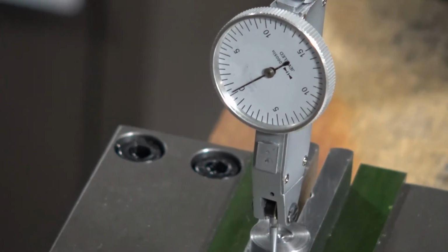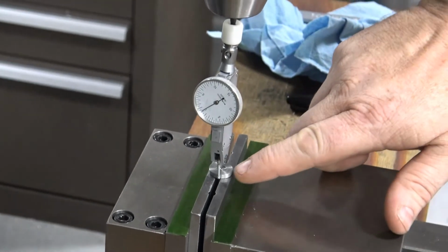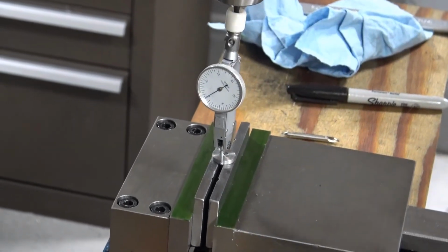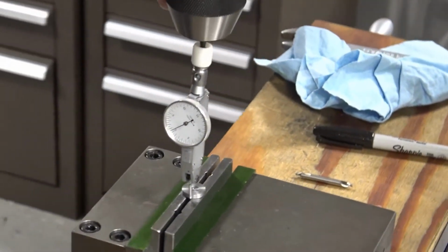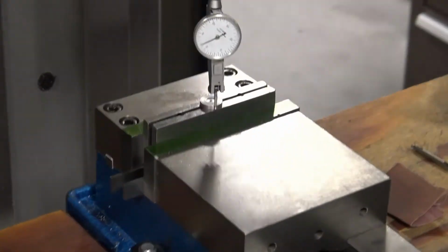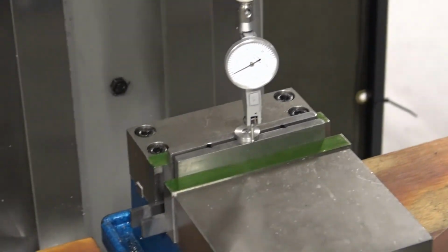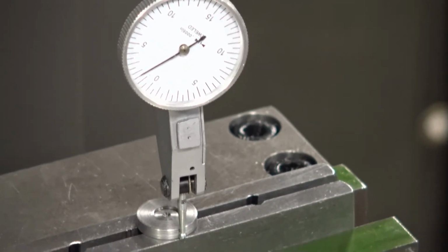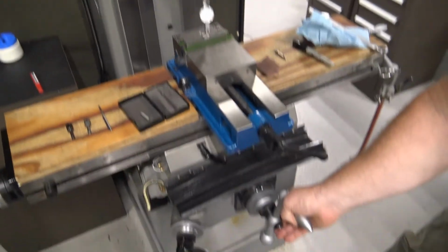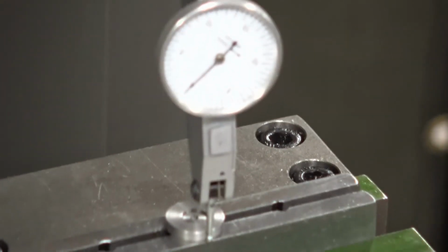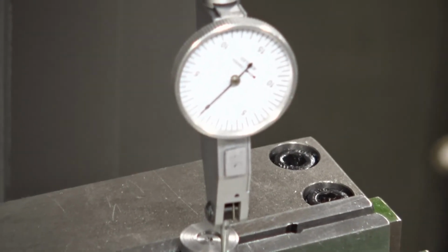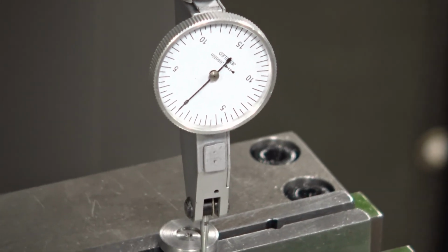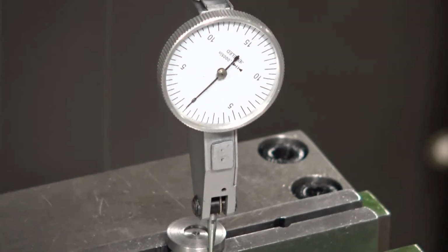So now we're going to repeat at the 6 o'clock position, and if it's off of 0, I'd like to adjust it and make it read 0. Okay? Now the direction that I have to move it to bring it into 0 dictates which direction I need to run the hand wheel. And again, right at this point, I don't care about the backlash.